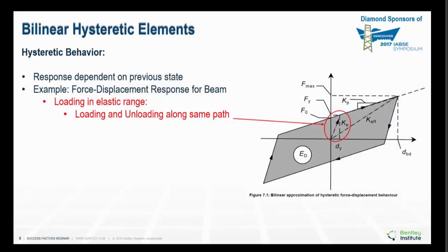The next analytical enhancement that we have is bilinear hysteretic elements. What is hysteretic behavior, and why is this behavior important? Basically, the hysteretic behavior's response depends on the previous state. As an example, if you look at this force displacement response of the beam, when the forces are small, we are in the linear, elastic range, and loading and unloading are on the same path, and we don't have any permanent deformation in the structure.